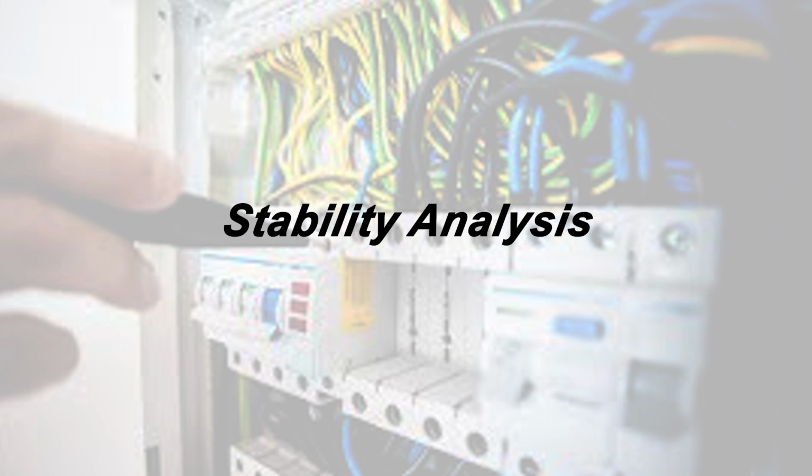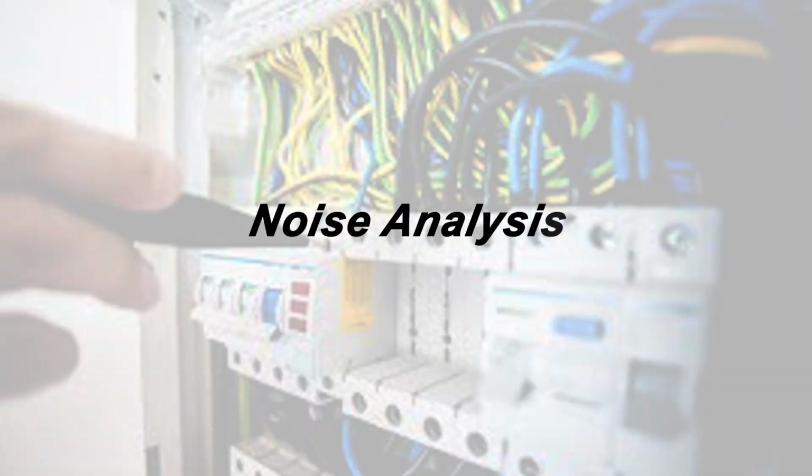Stability analysis: ensure that the amplifier remains stable across its operating frequency range. This involves assessing factors such as phase margin and loop gain. Noise analysis: for high precision applications, noise analysis may be performed to evaluate the amplifier's noise characteristics and signal-to-noise ratio.